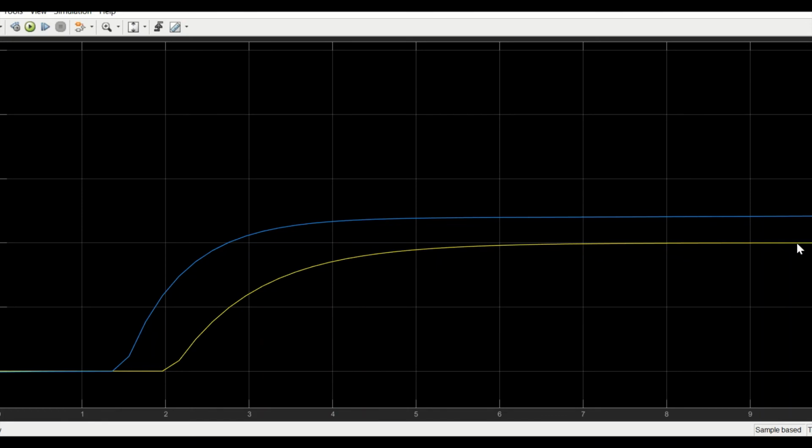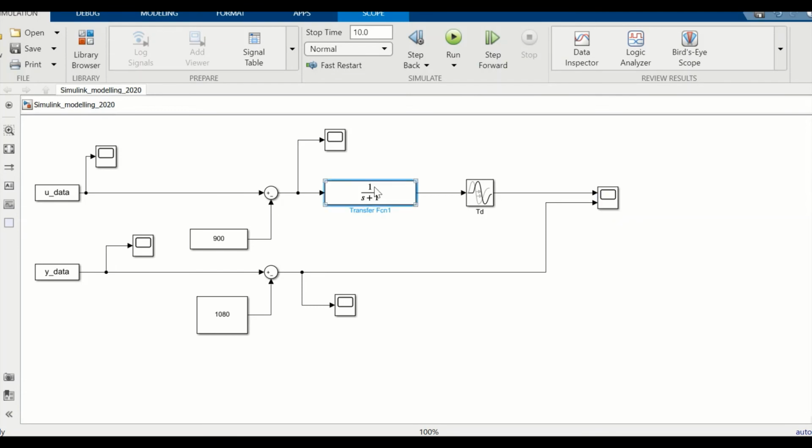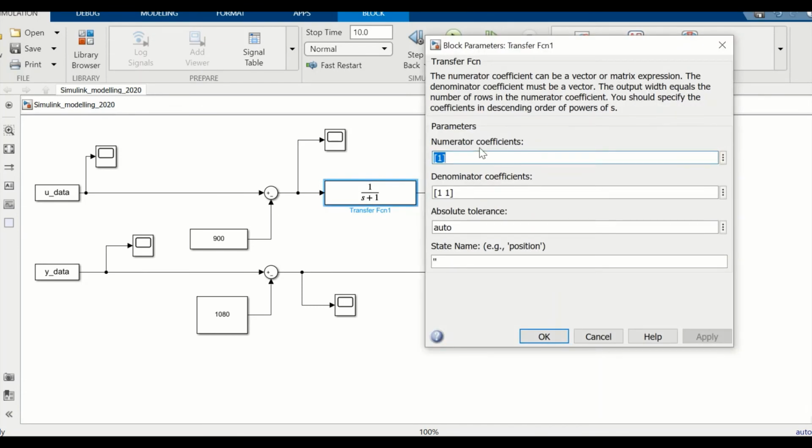So we're going to have to make this go up a bit this way, and we're going to have to make this go down that way. And we're going to have to probably, this doesn't look that much far off, but need a bit of adjusting as well. So the first thing to adjust is K. So K needs to go up, and probably needs to go up by about 20% or so. So if I choose my K now, and my K is the number on the top, make it about 20% bigger, make it 1.2.